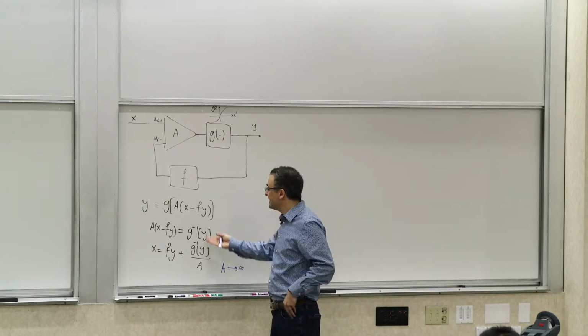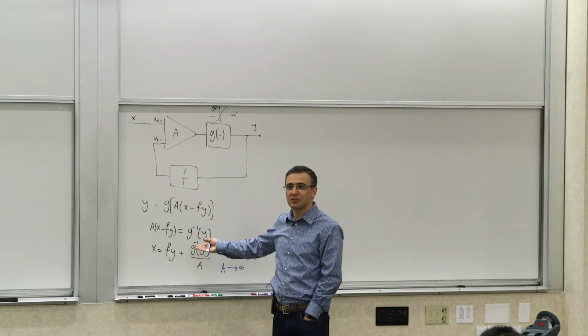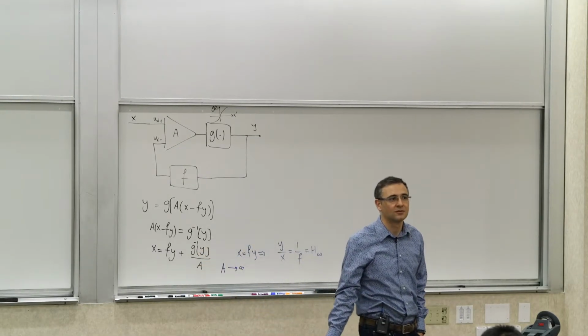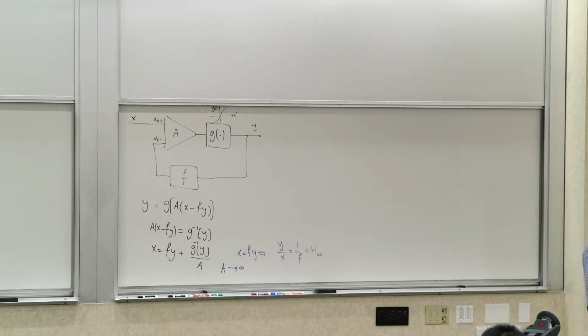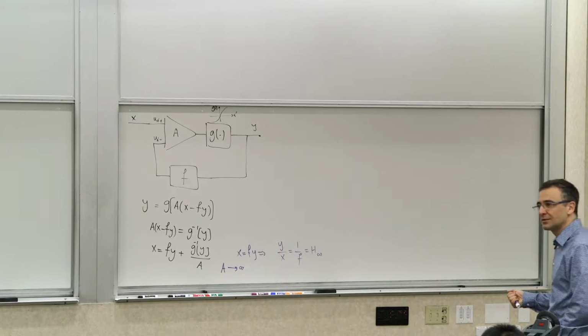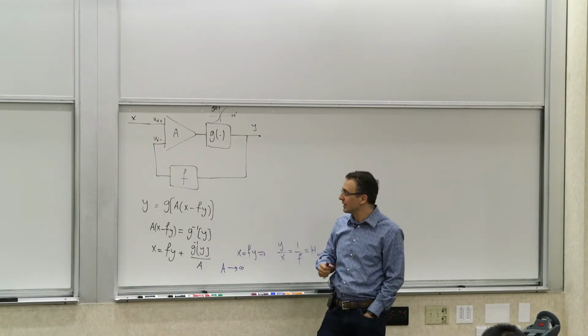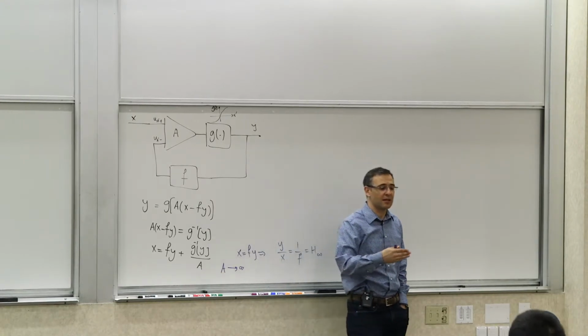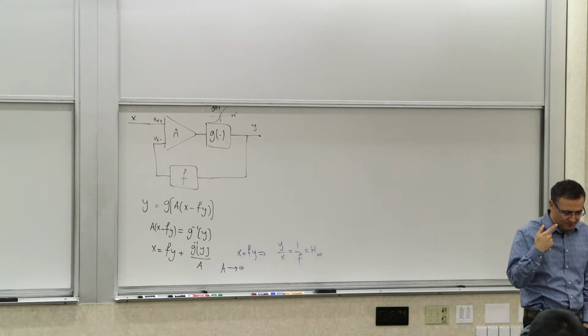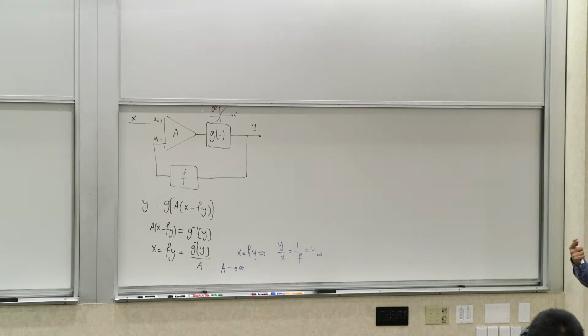By this action. And you can see it's very general. I mean, the way we wrote it is for any general nonlinear function. As long as your gain is large, you can basically suppress the amount of nonlinearity that you will get. And this was the main reason, by the way, that negative feedback was first used.